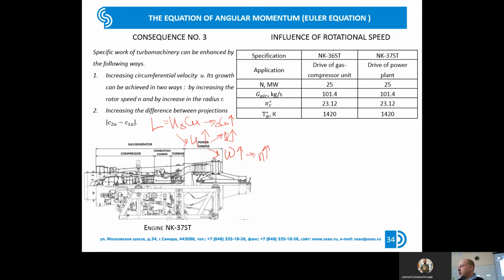The afterburner, nozzle, mixer, supersonic, yes, for supersonic bombers, but the initial engine was modified for ground application. The bypass was closed. The low pressure compressor was modified. One stage of the low pressure turbine was removed.